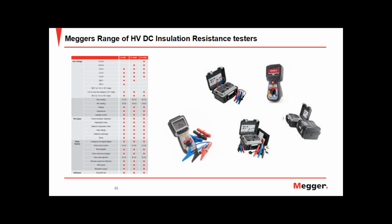Then we move up to the top right-hand corner, one of our most recent additions to the Megger stable. We have the MTR 105, which again is a handheld tester to 1,000 volts, and this is primarily aimed at AC induction motor testing, but also other rotating machinery, again equipped with the guard terminal. And then we have the S1. The S1 is available in 5, 10 and 15 kV outputs. Our 15 kV output provides you with the ability to test up to 35 teraohms in a portable unit.